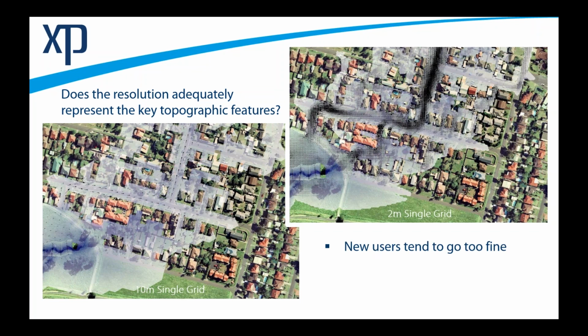I often find it's better to start big and then work down, a sensitivity test style approach. Yeah. See how that refined resolution changes your results. If it's not changing things dramatically in your area of interest, then all you're doing is increasing your run times unnecessarily. A question I get a lot is how fine can you go?